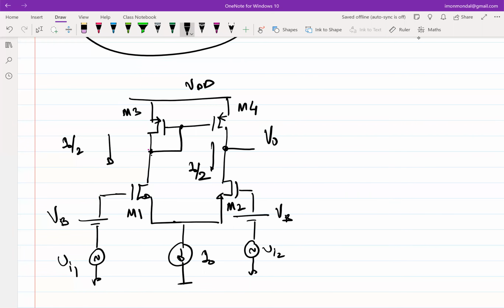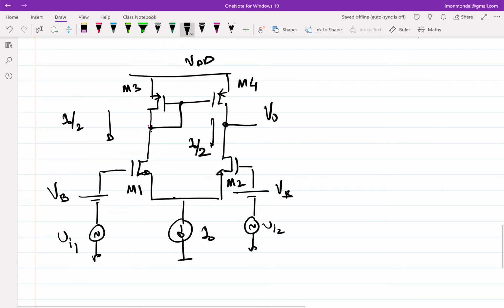Essentially, it boils down to the same thing, that we want large gain, because that's what we have been doing since the beginning of the course. If I Nortonize this circuit, I want to figure out the short circuit current and the open circuit current. For short circuit current, you assume that the output is incrementally shorted and go ahead with it. I'll do it in a slightly different way. I know that you are comfortable with this GM thing, but let me show you in a slightly different way. It's essentially the same thing, but hopefully it will give you a different way of thinking.